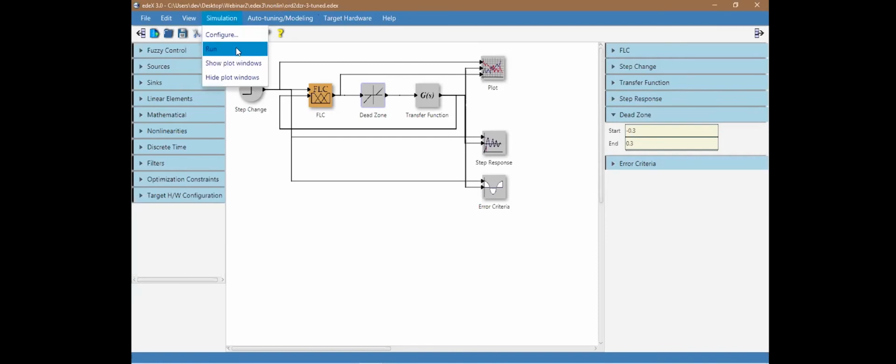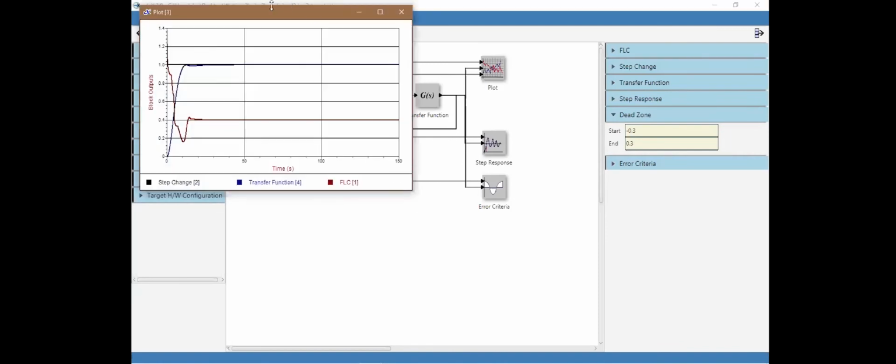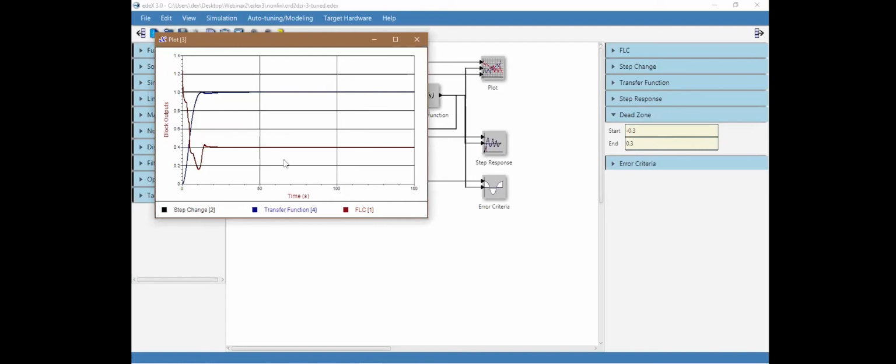So this is being tuned already. And you can see here, this is the unit step response. The blue is the process variable, and this brown is the control effort. You can immediately see how nonlinear the fuzzy logic controller is. It starts off with a very strong output to drive the process quickly to the set point, but it's intelligent enough to know that it has to brake quite dramatically before it overshoots, and so it settles nice and quickly and smoothly to your set point.